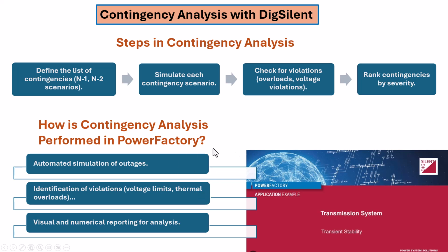As we know, DigSilent PowerFactory is a very powerful software, so it will simulate outages for you and identify violations for you, like exceeding transformer ratings, overloading of transformers, or exceeding voltage drop limits, and other scenarios as well. After running these analyses, it will generate both a visual report and a numerical report to help you, the operator, the power system engineer, to quickly assess and address the issues that will arise based on the particular scenario.